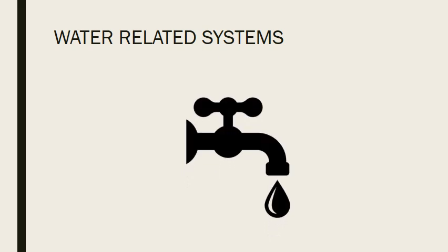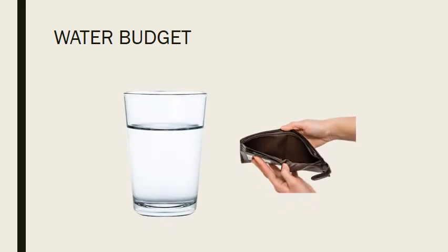Now, let's move to water-related systems. The procedure to properly analyze this concept will follow the same methodology of discover, goal workshop, evaluation, and implementation as the energy systems did. For the discovery phase, projects should calculate an estimate for water usage for the building. This is also known as a water budget. This water budget is a project-specific method to calculate water demand for a specific amount of time, which could be a week, month, or year, and a quantity such as kilogallons or liters.